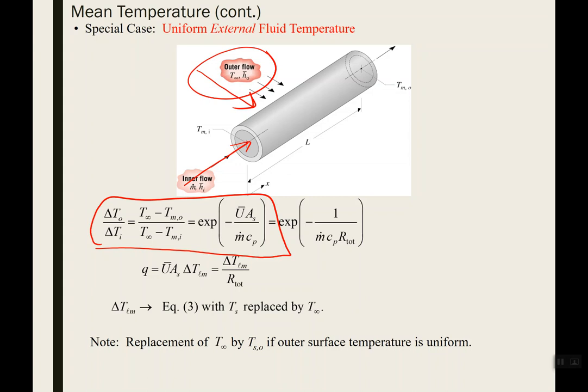So that's just basically what's happening in this situation. There's convection happening on the outside wall, there's convection happening on the inside wall, and then there's also conduction happening through that wall. So we have to factor in those other thermal resistances. We have to get from our T infinity, so notice we're no longer using surface temperature in this equation, we're using this outside fluid ambient temperature. So we'd have to solve for our U that factors in the two convective thermal resistances and the conductive thermal resistance. But then the equation would basically become the same. We're just factoring in these other thermal resistances.